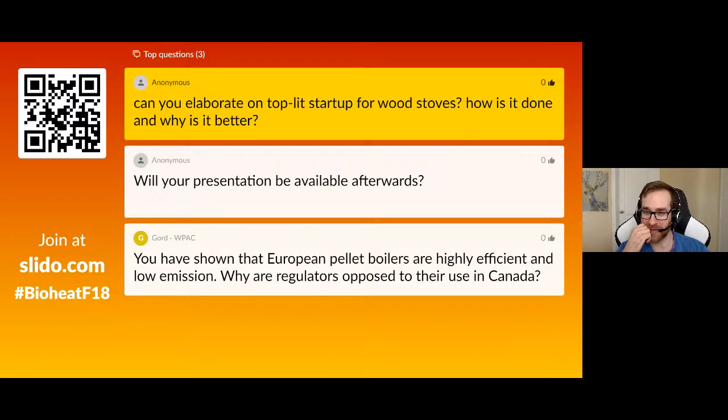Yes, there was a special report also available on the IEA Bioenergy Task 32 website that was done by Thomas. Essentially, instead of having the paper and the kindling at the bottom of your stove and then putting the larger pieces on top and lighting that fire, you do the opposite. You simply put the big pieces at the bottom, set the kindling on top, and then light the newspaper.